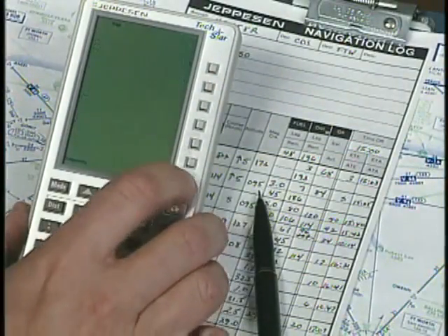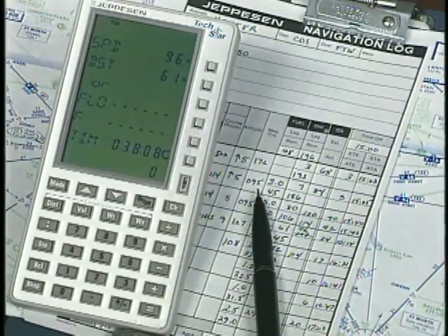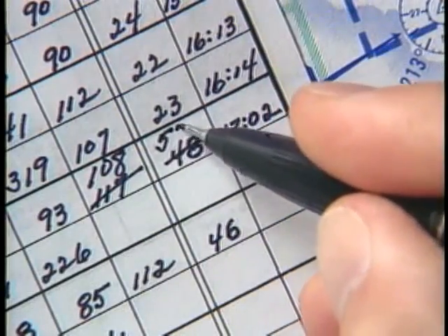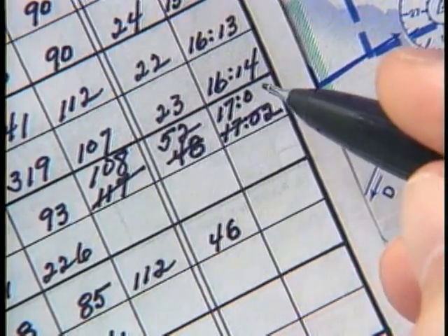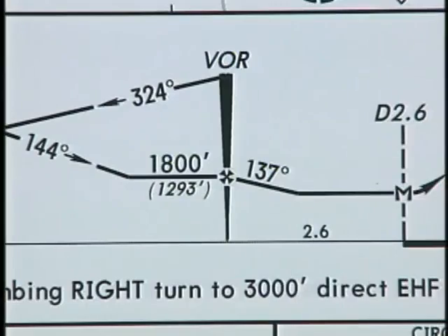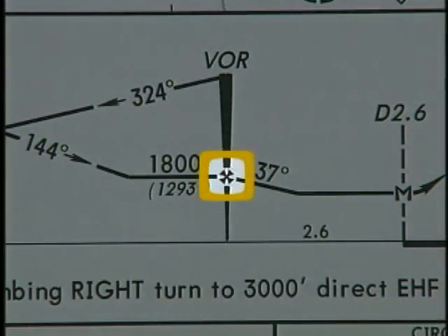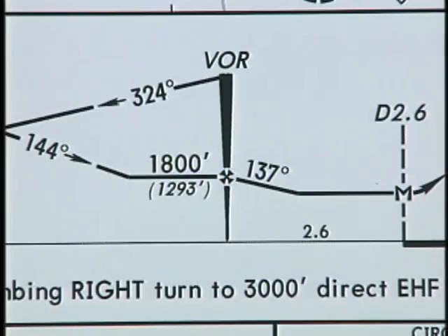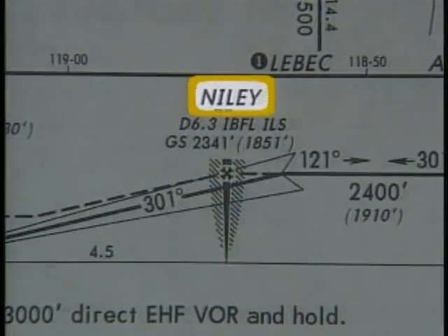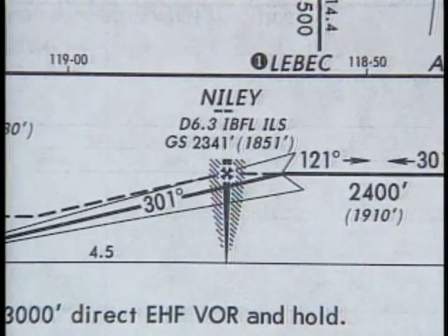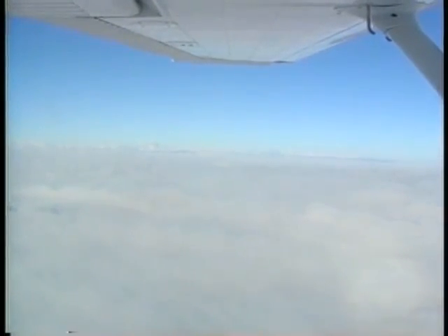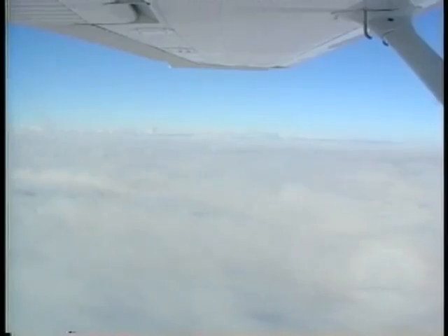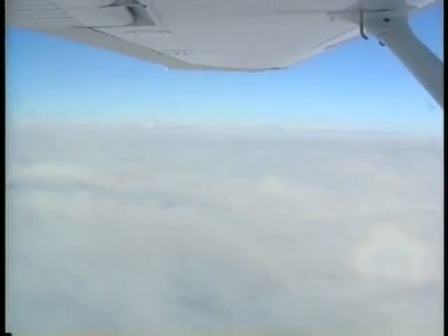There are other reports which you need to make when not in radar contact. For example, you should report a new estimated time of arrival if it changes by more than 3 minutes. You should also report the final approach fix inbound on a non-precision approach, or the outer marker, or the fix used in lieu of it on a precision approach. In order for ATC to follow your progress and keep you separated from other traffic in a non-radar environment, regulations require that you supply position reports.